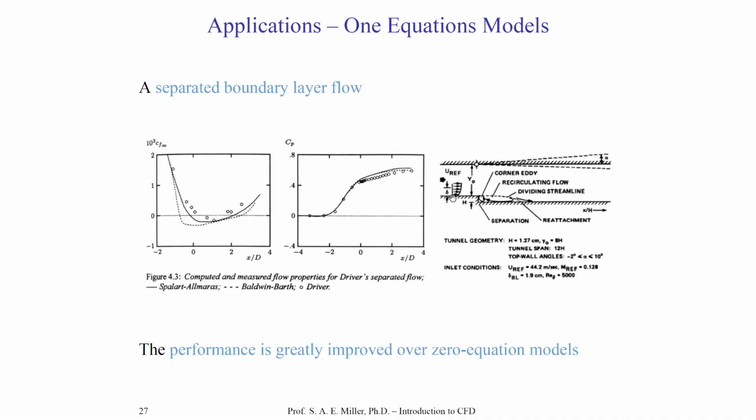particular backward-facing step. The flow moves from left to right. There's a shear layer on the top of the tunnel, and here's the backward-facing step of height h. Now they're making the measurements along the base of the backward-facing step. They've normalized the results by the step height h. The distance x goes from, of course, the position of the step downstream. For positive x over h, or x over d in this case, they're showing the results downstream of the step. So that's what's on the x-axis.